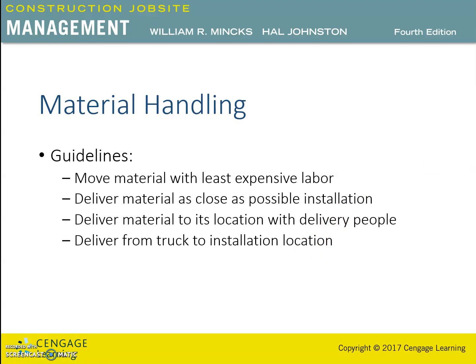The steel fabrication, such as a column assembly, is lifted by the tower crane directly to the installation location and immediately bolted into place. Extra coordination is needed, however, to ensure that the correct fabrication is available and shipped at the time needed, and the installation location is ready for the material or equipment upon its arrival.